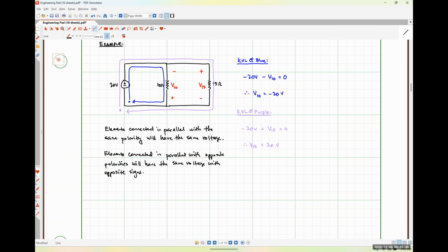You may not have realized it, but in the 120 series, every circuit that you were given, except for possibly the alligator problem, depending on how much of an ass Dr. Schwanbaum felt like at that particular day, had only a single voltage source. Whenever you have everything excited by a single voltage source, essentially all of your resistors are always just going to have the same polarity as the voltage source. So you never ran into a situation where we had to take that into account.